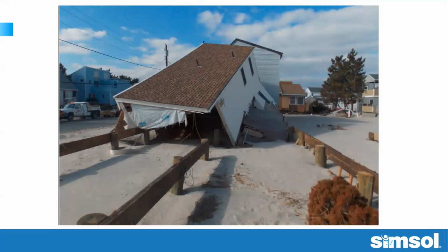Now, this one, again, take a look at it. We've got a lot of damage going on here, but again, look at the roof slope. I would challenge you to find a shingle missing on that roof slope. This house, again, look at the siding on the house behind it, directly behind it. You don't see any siding missing off of the house behind it. You don't see hardly any siding missing from the damaged house either, and the elevation that you see. Going further to the right in the photograph, notice the roof surfaces there look fairly intact. The trees still have a good many leaves on them. They're still vertical. Again, in this particular photograph, the Atlantic Ocean is behind me.